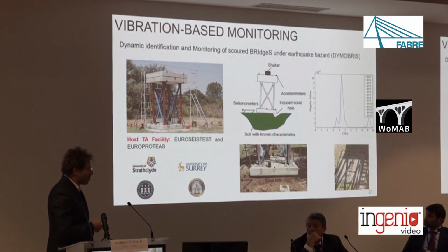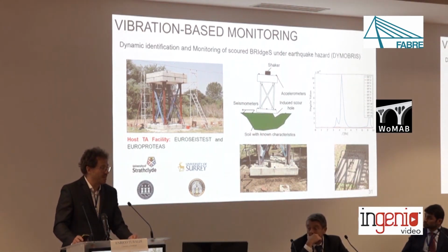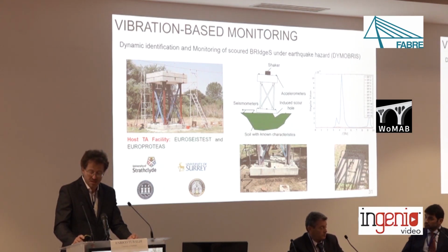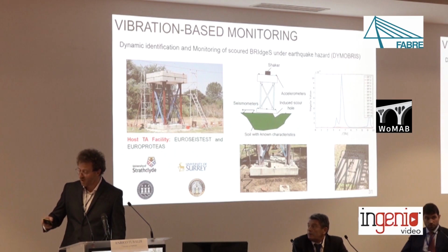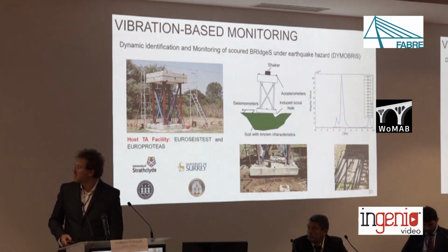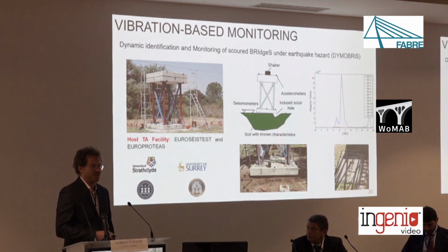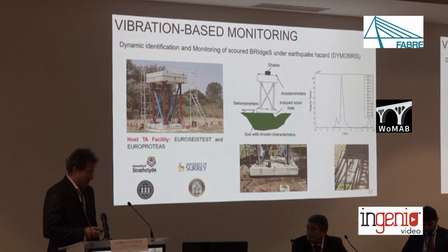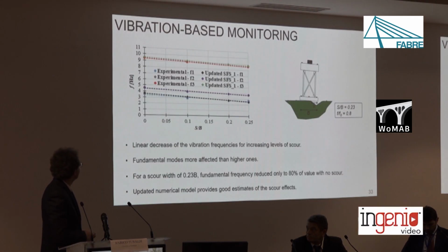And then we've done some work over the years on testing vibration-based monitoring approaches for bridge scour. This is a European project, a CETA project I led a few years ago. We accessed the Euro-Proteus facility, this prototype located in Thessaloniki. We artificially induced the scour by excavating below it and measured the changes in the frequency of vibration of the structure through accelerometers mounted at the top.